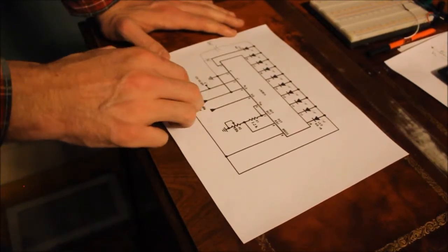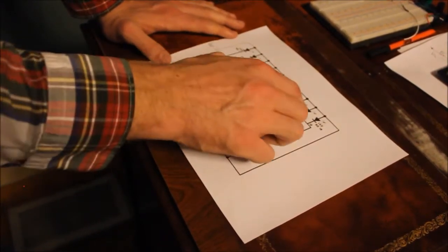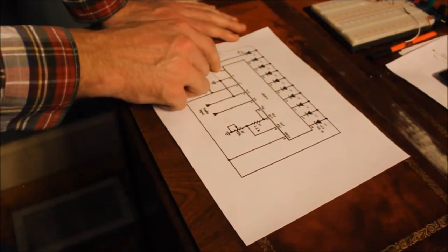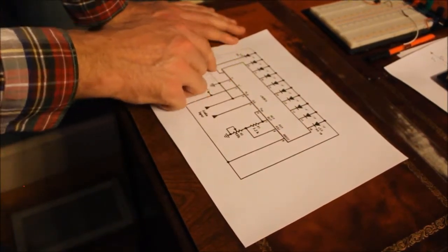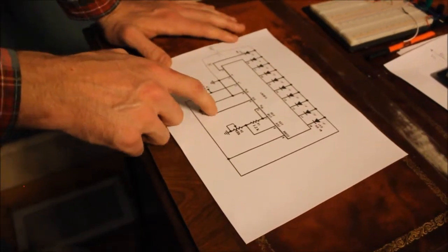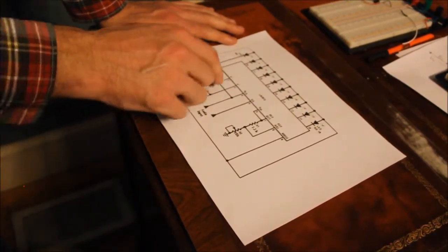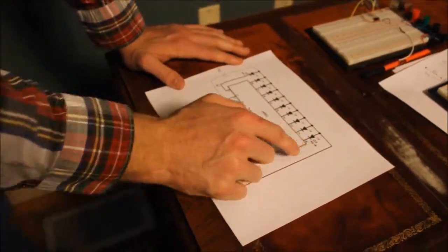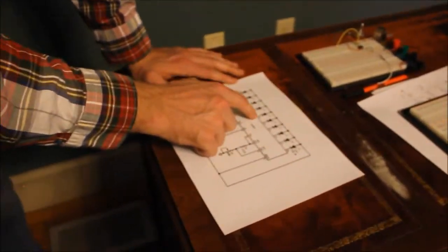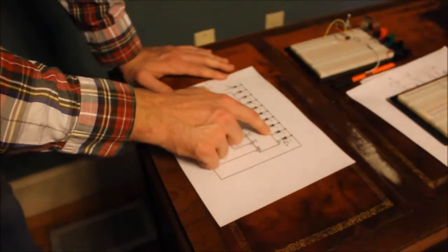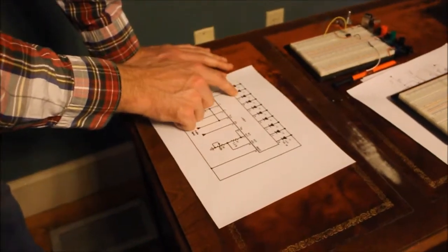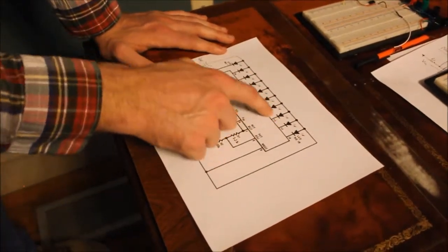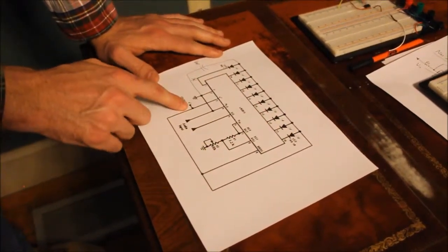Essentially what this chip does is it has a comparator at each of these inputs, 1 and then 16 through 18. If this signal in is equal to V plus, all 10 of these will be lit up. If it's equal to some fraction of V plus, less than V plus, a corresponding amount of these will be lit up. So it basically shows you the strength of the signal coming in compared to the input voltage here.